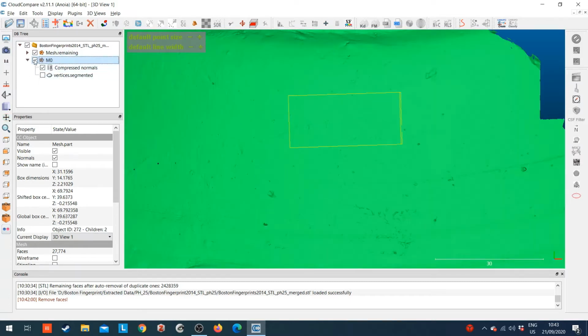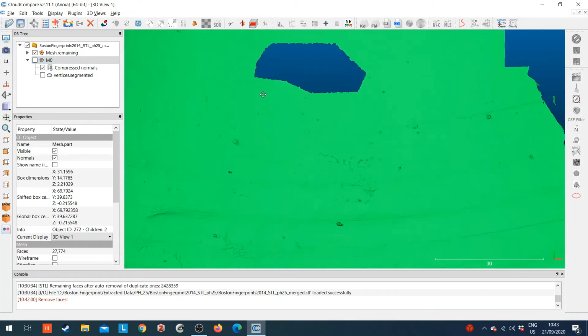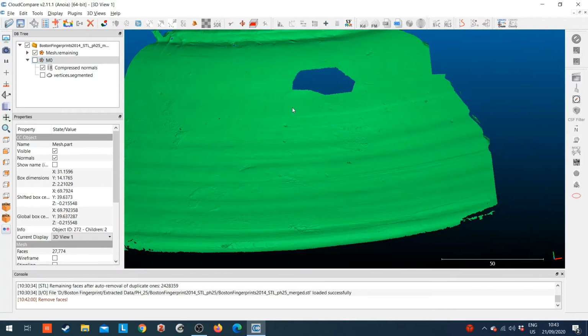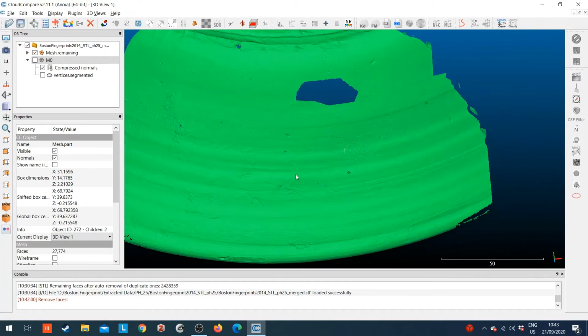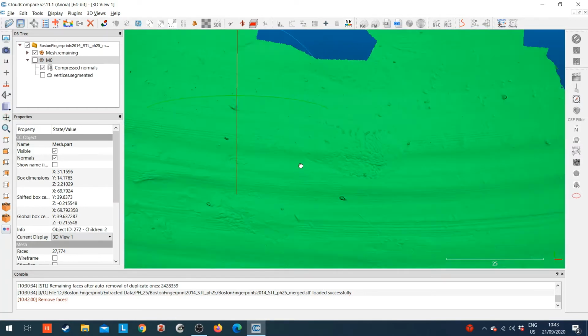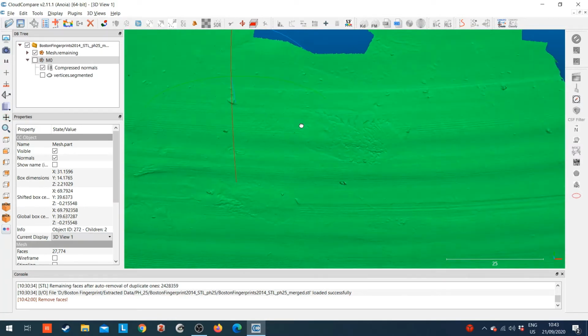As you're segmenting each of these out, it's easiest just to go from the remaining mesh from before. Otherwise, you'll end up with all sorts of duplicates and very large file sizes. So just stick with segmenting from the same mesh.remaining for now.